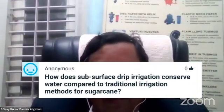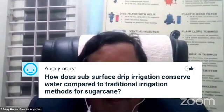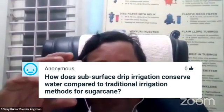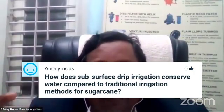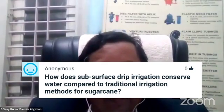Okay. And how does subsurface drip irrigation conserve water compared to traditional irrigation methods for sugarcane? Yeah, in the conventional method of flood irrigation, we allow the water to move through the channels. So there is a lot of wastage of water. If you take 1,000 liters of water, hardly about 300 liters is actually getting into the crop. All the remaining water is getting wasted in conveyance and water logging. So we are wasting water.